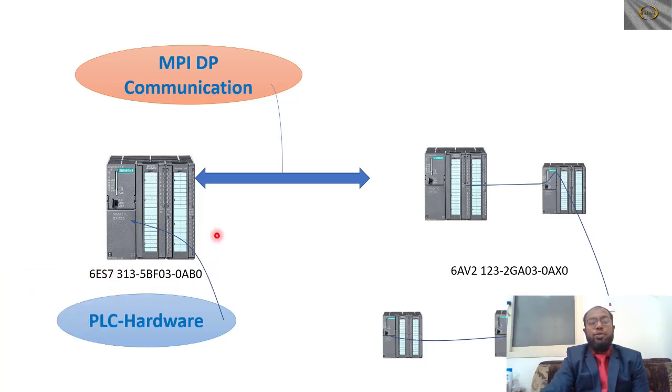And here we are using this, the main PLC or master PLC of the foaming plant, and here we may use the wet station PLC of the foaming plant, and this we may call the dry station PLC. These are all the dry station PLCs number 1, number 2, number 3, number 4, like this. Suppose here we want to do some operation, then it gives the signal to the master station via MPI communication protocol using the Profibus cable.